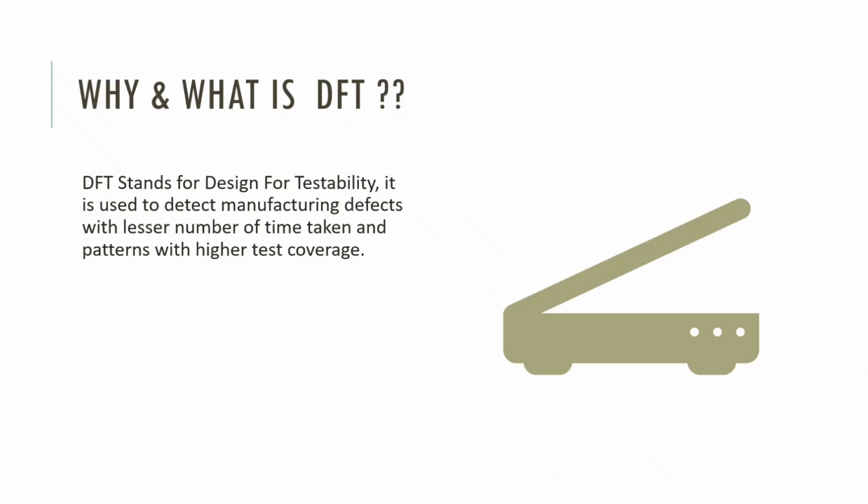Now here comes why and what is DFT. DFT stands for design for testability. That means it is used to detect the same manufacturing defects with less time taken, fewer patterns and higher test coverage. To give an example, we saw that in the NOR gate there were some defects due to manufacturing. To detect such defects, we modify the design, we add some design in such a way that post manufacturing, we are still able to detect such defects. So that is DFT for us.